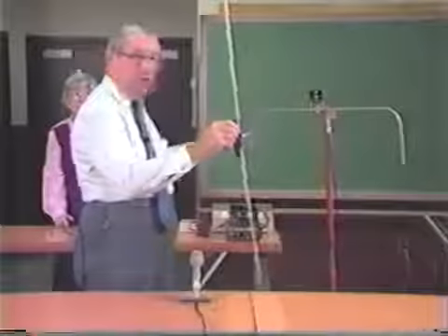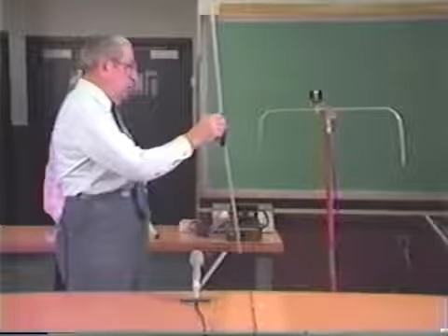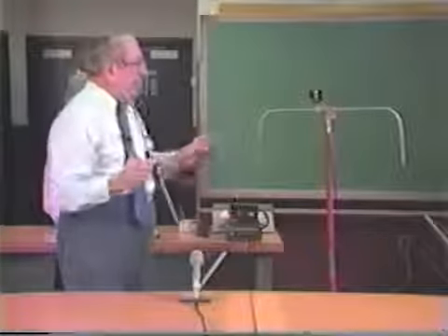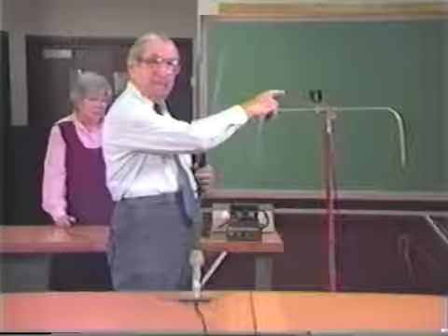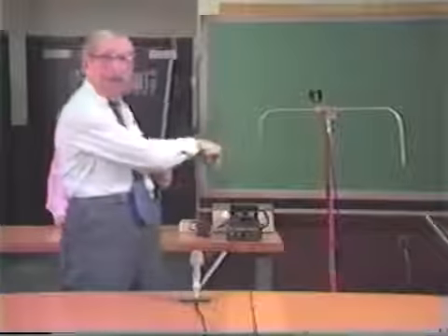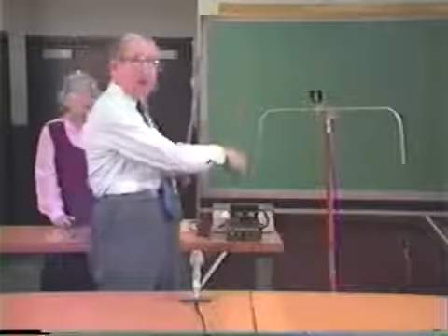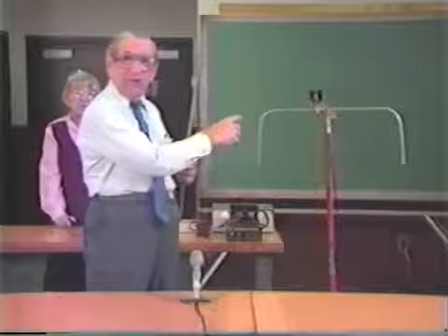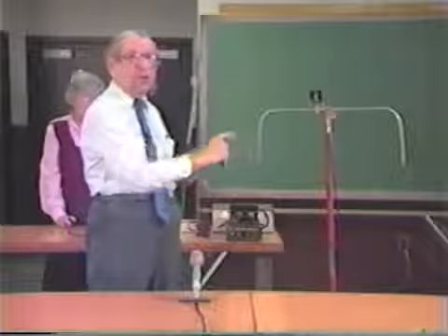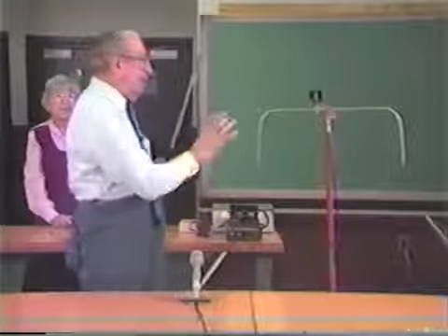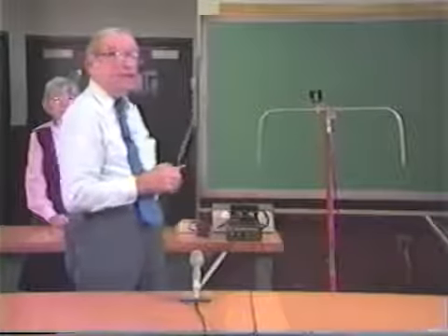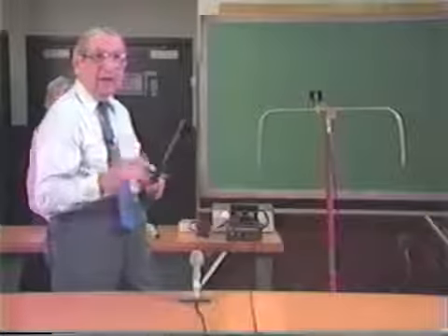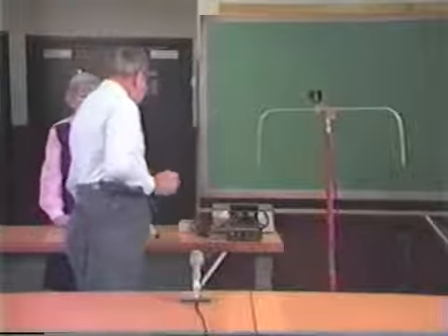There is a little current being radiated. If I put this very close to it, I'm sure you'll see a little bit of light, because don't forget, as I pointed out to you before, the current is maximum at the center, falling off to zero at the ends. But there is a little bit of current here, so there is some radiation from this bent portion, but a very minimal amount. But that's the way the radiation takes place within the current portion of the antenna, and it's very important that you understand that. Okay? Now we're going to go into the vertical antenna.